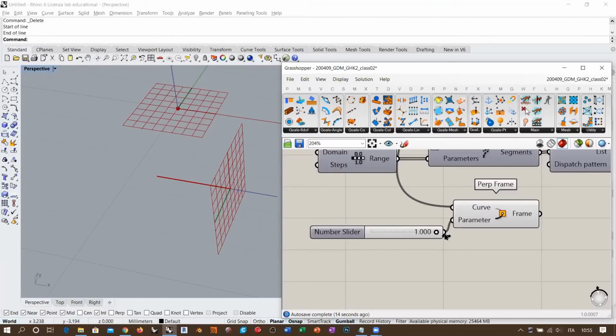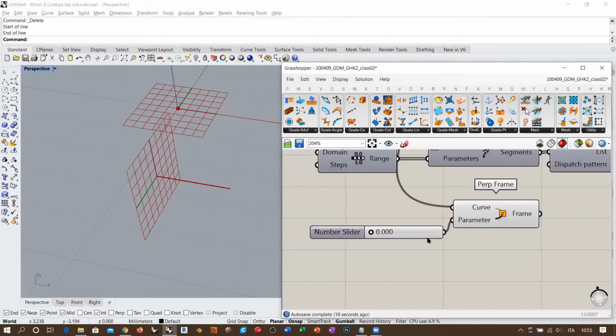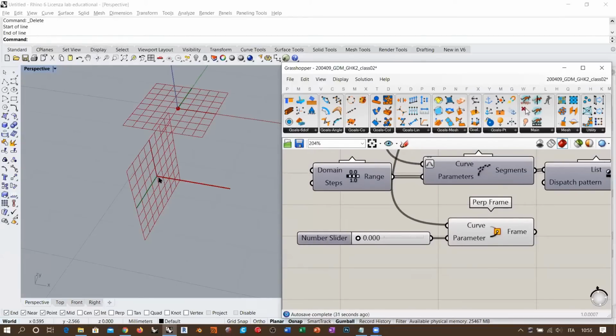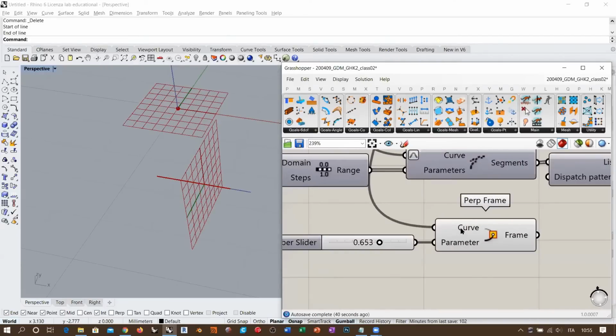For straight lines, there is no need to reparameterize normally, because as there is no higher degree equation basically behind them, there is a linear flow along the line. Grasshopper normally assumes that this has a 0 to 1 domain. Okay, so this is the explanation. Of course, you can reparameterize.